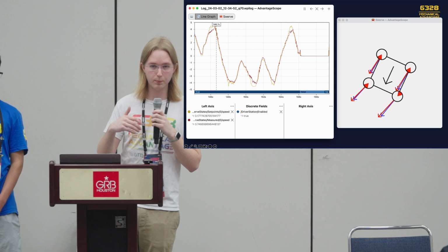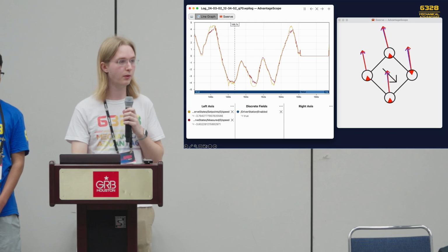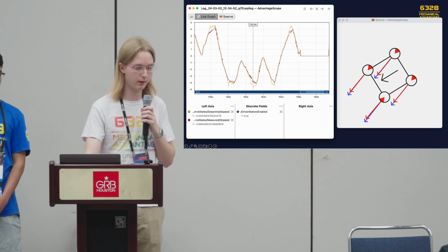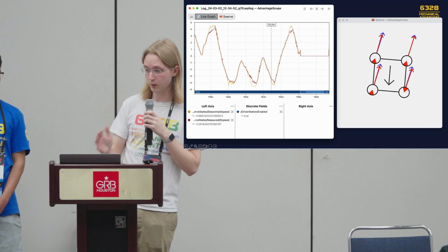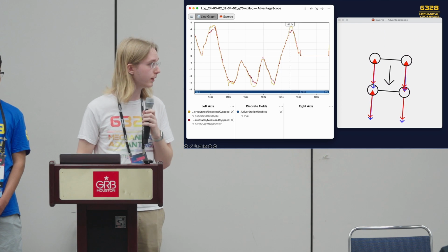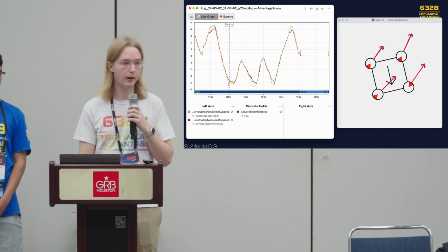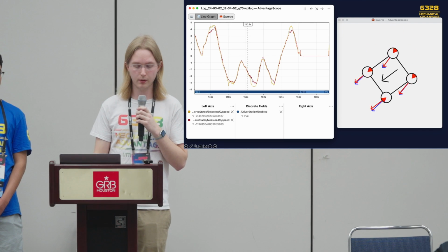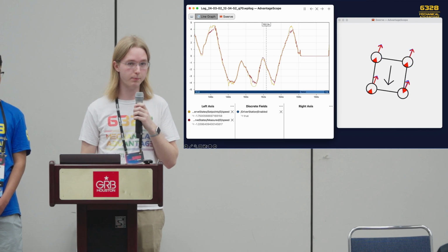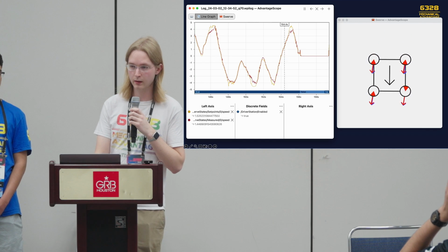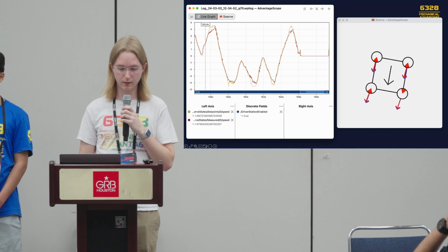And now, let's say we applied those new gains to our swerve drive, we can check the performance of it in AdvantageScope. And when tuning a swerve drive in particular, there's this built-in visualization that can be helpful for that, showing the vectors of how each wheel is moving. So here, these in red are the measured positions and velocities, and in blue are the set point states.